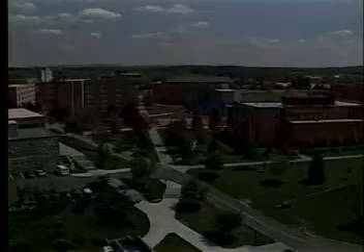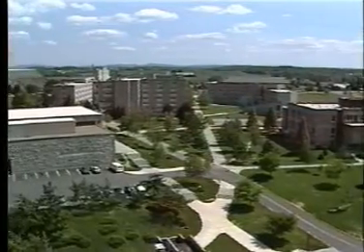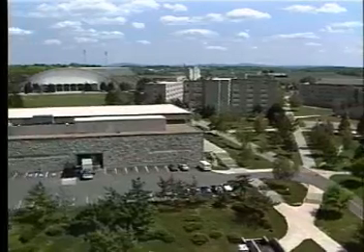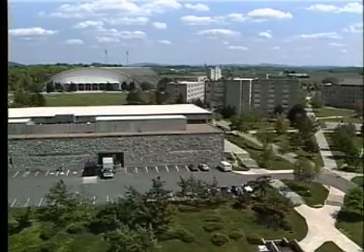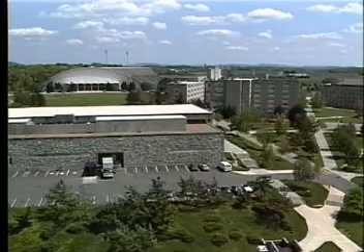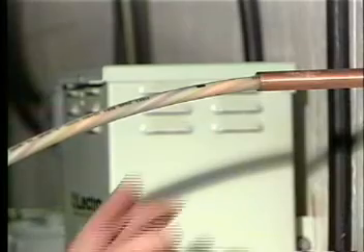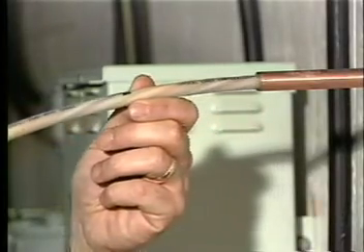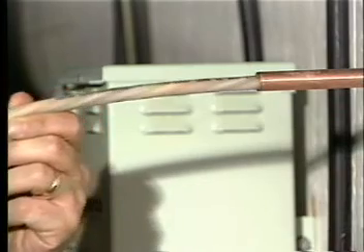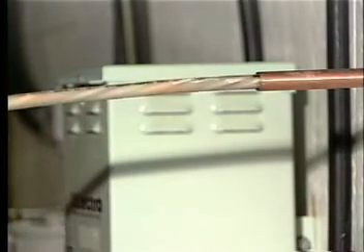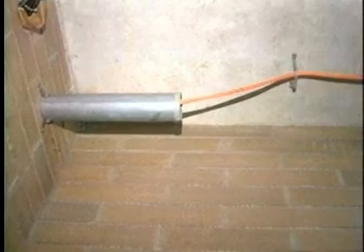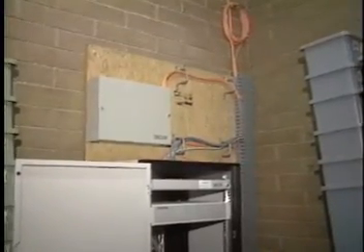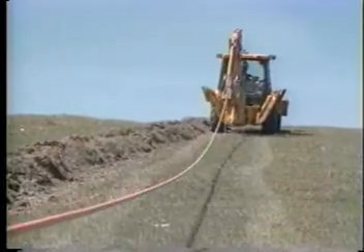In our previous design video, we planned a fiber optic link between two office buildings. In this, like many such installations, a number of cable placement types are used. Plenum cable runs horizontally on each floor, interconnecting riser sections, users, and system electronics. Backbone cabling typically involves riser-rated cable being distributed from entrance facilities to the horizontal cross-connects located strategically on each floor.